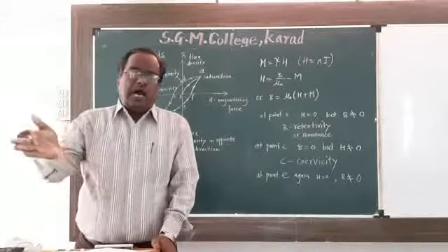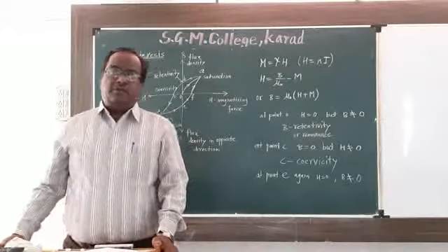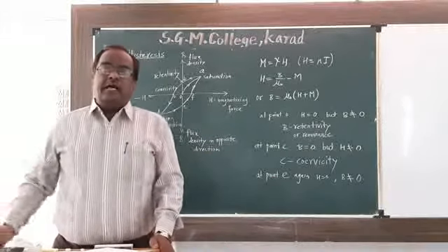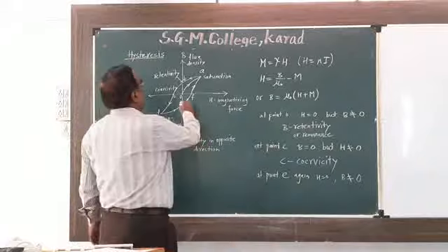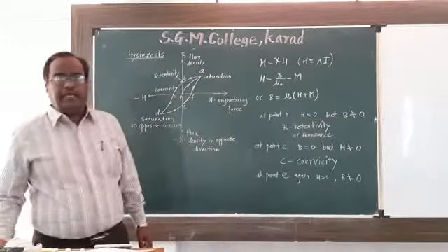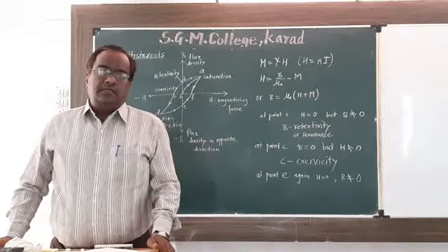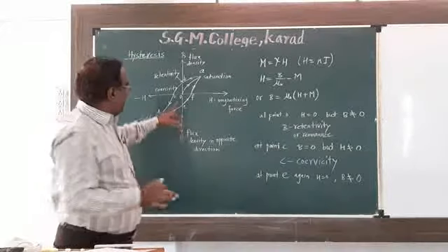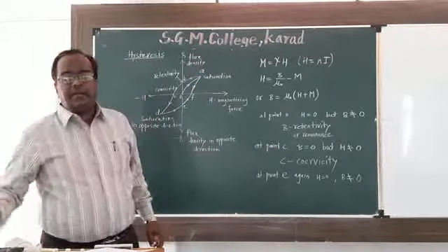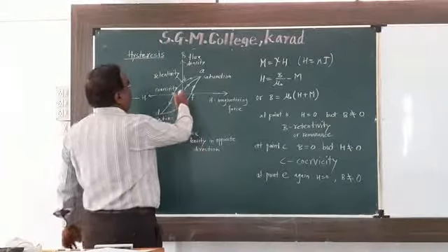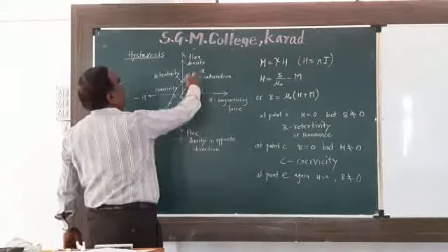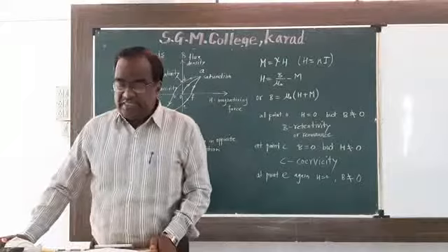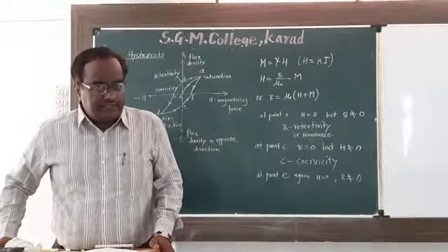Axes of domains are in the opposite direction in the ferromagnetic substance, but domain structure remains present. And if we increase the value of current again, then we get the curve EFA. By increasing the value of current, magnetic flux also increases and we reach point A again. Now this whole loop O, A, B, C, D, E, F, A is called the hysteresis loop of a ferromagnetic substance.